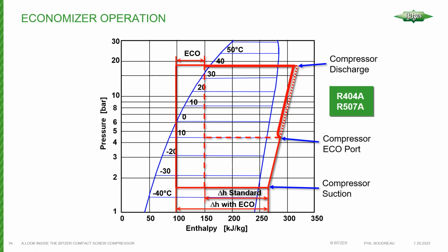So let's just say, to pick a number for an example here, 25 to 30% of the distance from the suction end of the compressor in, we could actually inject a flow into the compressor there. A side load, we'll call it. But we're going to use it in this case as an economizer. So your normal cycle would look something like this. Of course, these are red lines and my pointer's red too, so that doesn't help.